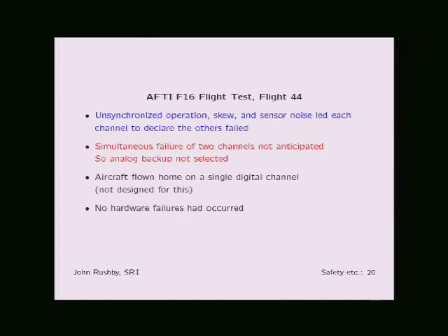Here's one problem that happened with an unsynchronized system. This was a test flight of the F-16. You had multiple computers, and they were all sampling the sensor at different times. There was some skew in the samples because of the lack of synchrony. And what happened was every computer declared that the other ones failed, because there's not going to be any agreement.